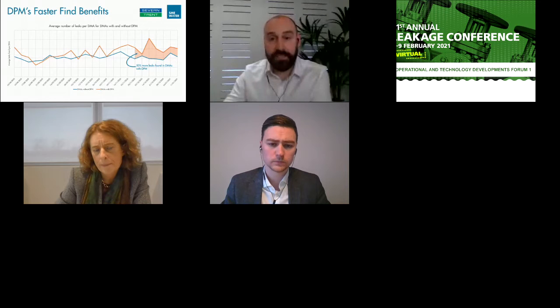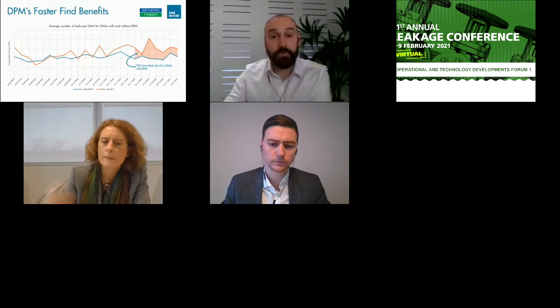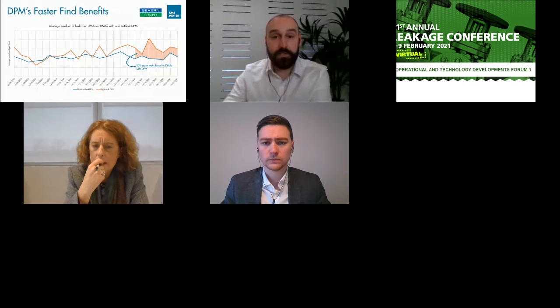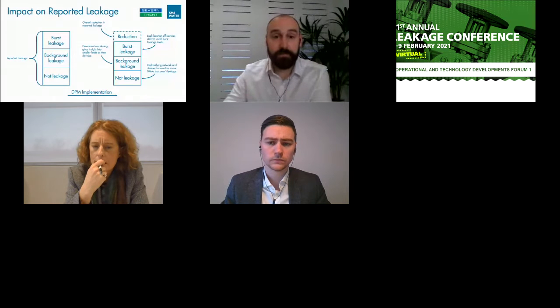Adam's talked about burst leakage, and by finding these faster, being able to get the most from the resource that we've got with our localization area hotspots, we can start to reduce that. We've also, in Severn Trent, in some of the DMAs, had loggers out for 2 years, 2.5 years in some cases, and we're starting to see some real insights.